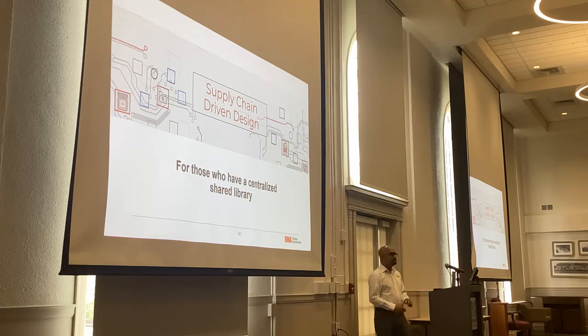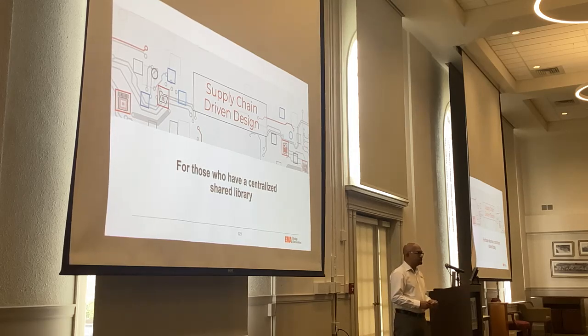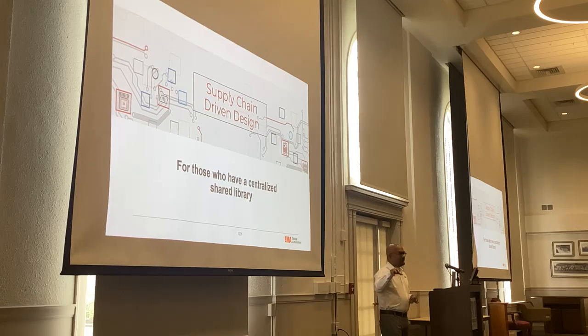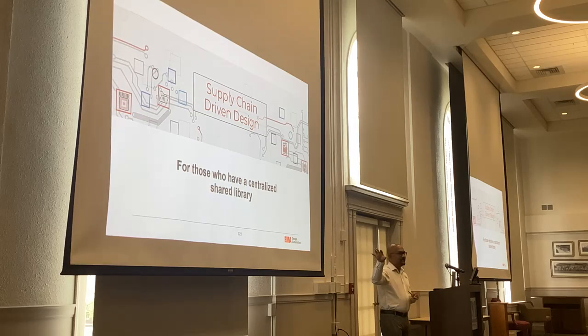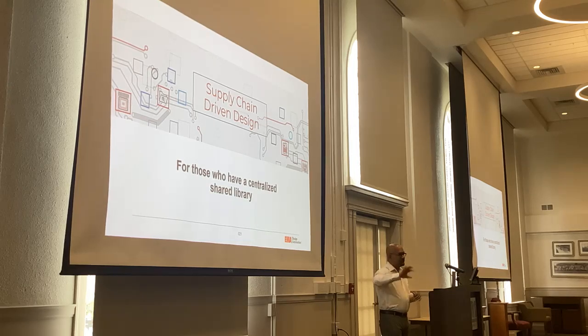Excuse me. One quick question. When Silicon Expert finds an alternate, does it actually confirm the footprint match? Yeah, so it basically tells you if there is any difference in package. To get to your question, the OrCAD CIP tool will compare symbol and footprint and tell you if there are any mismatches. What Silicon Expert does is it tells you if there are any pin mismatches, at a high level. But the OrCAD CIP tool will get you more data.